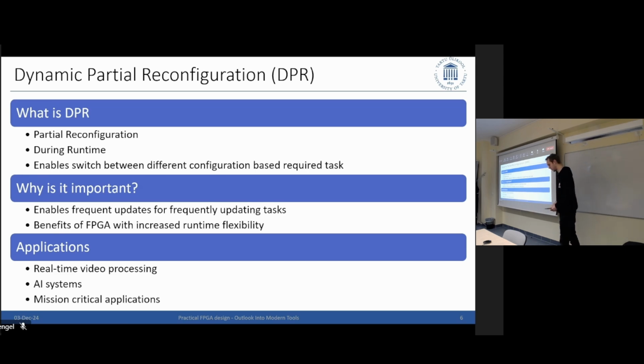This is why it is, for example, critical in space missions. When you reconfigure an FPGA, there's a chance that you get stuck in a reconfiguration state, and then you can't get out of it anymore easily. And then you're like, yeah, I reconfigured, I wanted more performance, but I have nothing anymore.